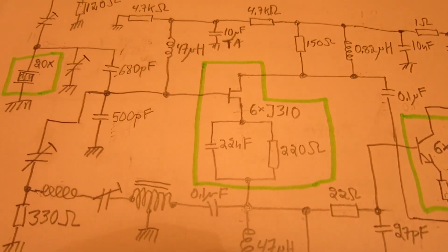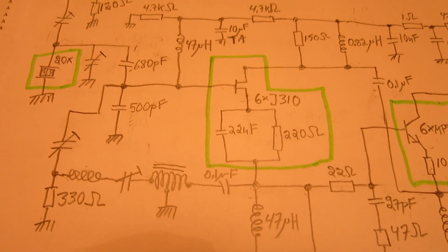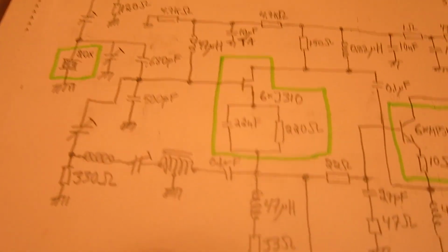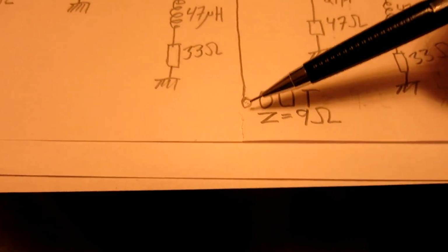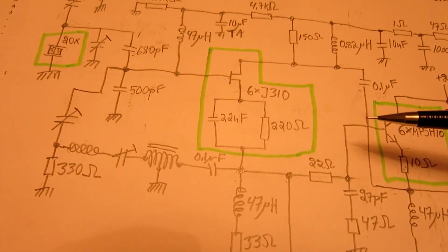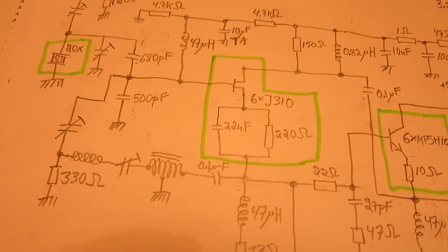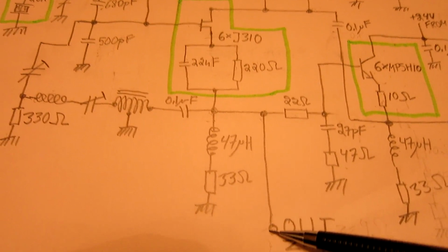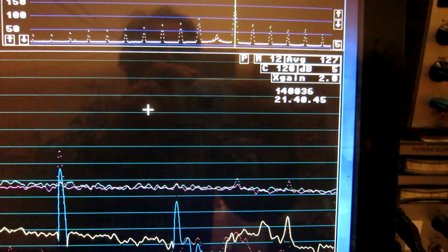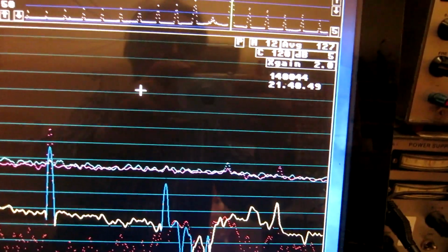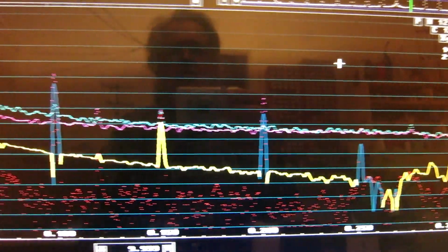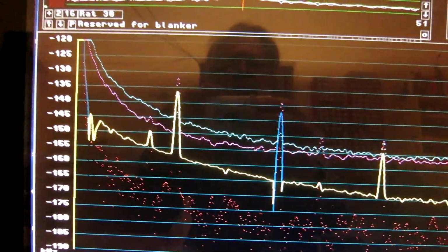As a first step, I'm just now looking at the sideband noise when measuring at this point the output, and I have disconnected the amplifier that normally is connected here. I have collected the correlation spectrum for 21 hours now, and this is the phase noise, and it looks like this.